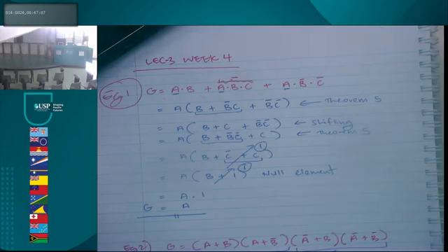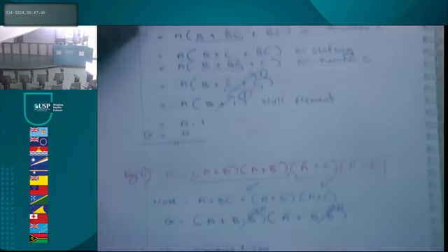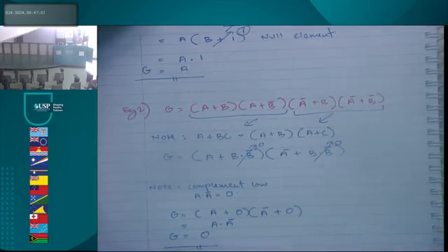Okay, let's have a look at example 2. Let's do a warm-up on example 2. Guys, once again, very similar thing. How many gates? 4 OR gates, 1 AND gate, and then you have 1 for A bar, 1 for B bar. So 4 gates, 1 AND gate, 5, 6, 7. 7 gates. And in the end, our final reduction comes to what? G is equal to 0. So we just connect G to ground. You don't need any gates. Again, 100% savings. All right? Okay?